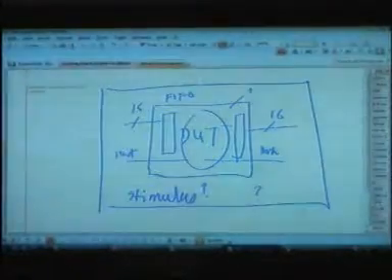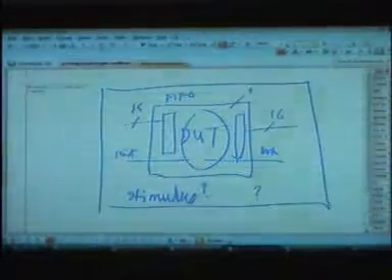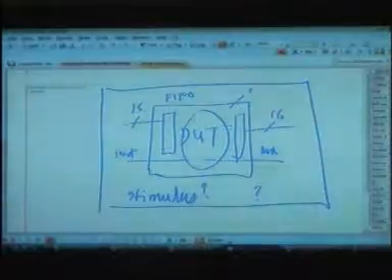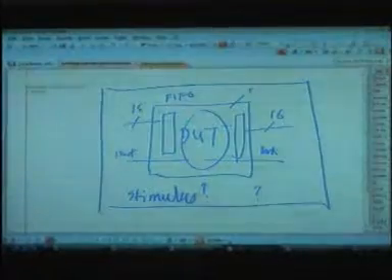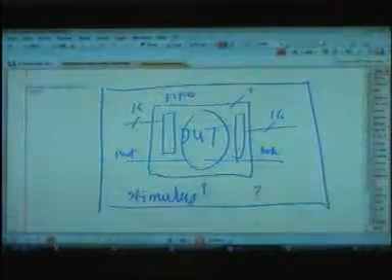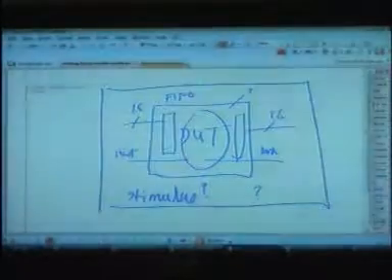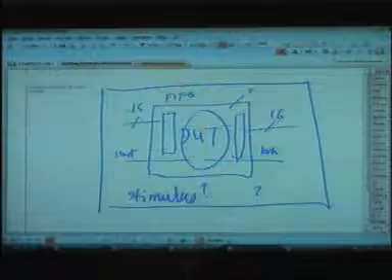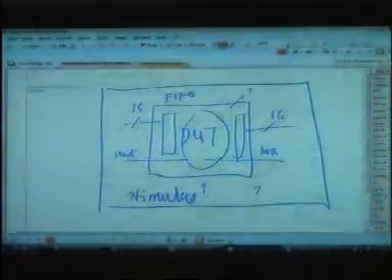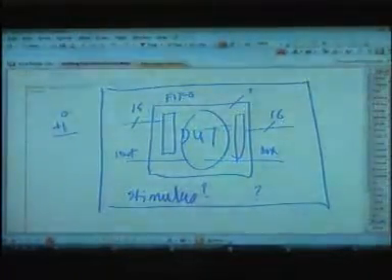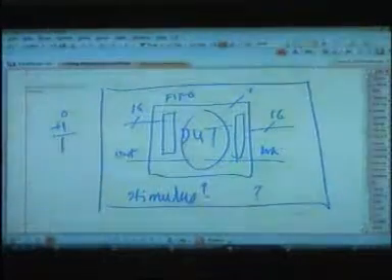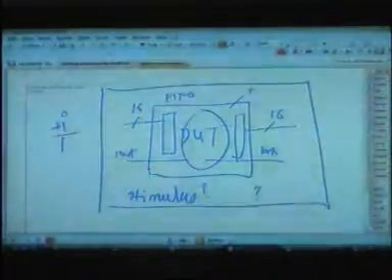The coverage is very different. For example, I give you sorting and you only test for all zeros. This is a test, you say it's working because at the output I'm getting all zeros. But you have not tested the design. All zeros, all zeros. Obviously, even if you have missed something, it will never show in your design, yet you say it is working. People will say, oh, I have designed an adder, if you add 0 plus 1, it says 1. So it means nothing. You have just tested one case. So challenges are in testing.